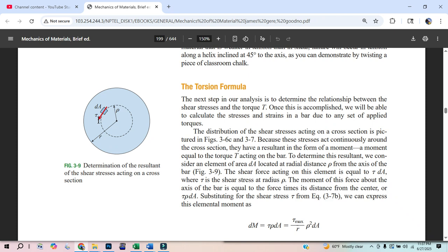Now, the first thing you need to do is find the force. Know that shear is a force, but only due to the little area it's acting on. And what we've shown is that this area is going to be different than that area, and different than this area, because once we integrate, look at this ring. That ring is smaller than this ring. That's part of the integration. Okay, so tau is shear stress, which is in units of force per area. That's pounds per inch squared.